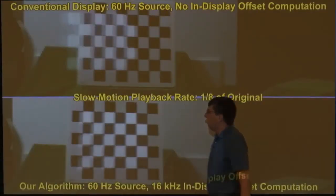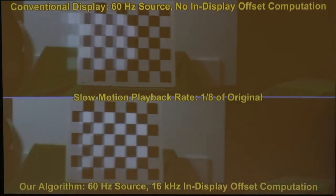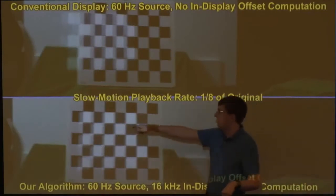So in this particular system, we used all aluminum pieces for mounting everything. And as a result, the display was moving along axes that weren't being tracked because the aluminum it was mounted on was deforming. And so we later replaced that with steel to fix that particular issue. So if we had actually stopped moving in either of these particular cases, both images would diverge in a similar amount. So this particular offset that you're seeing is actually because of